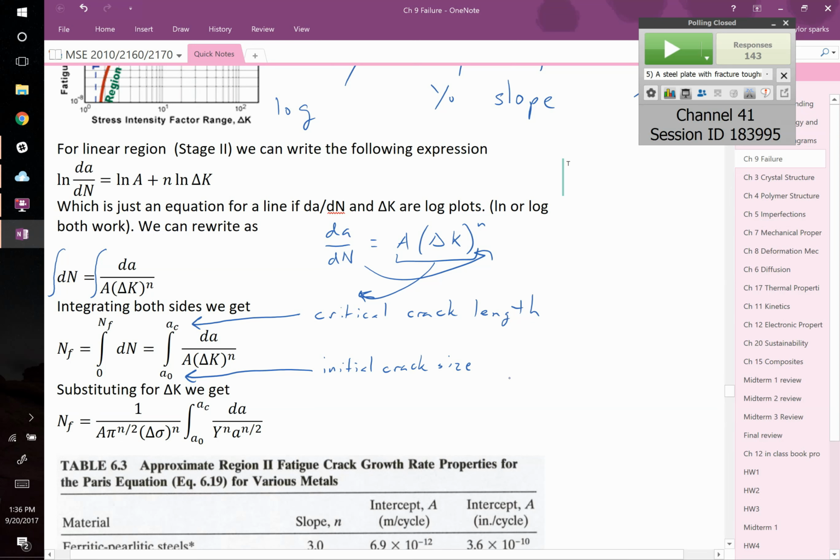Remember, we said K1C, a fundamental materials property, equals your Y times your applied stress multiplied by the square root of pi a. We can solve for the critical crack length by just plugging in your maximum stress. So if it's cycling between 500 and 200, it's going to break when it's at the top of its cycle at 500, right? And then all you have to do is solve for a_c. So you know how big the biggest flaw can be before this thing fails. Is this making sense, how this is all coming together?